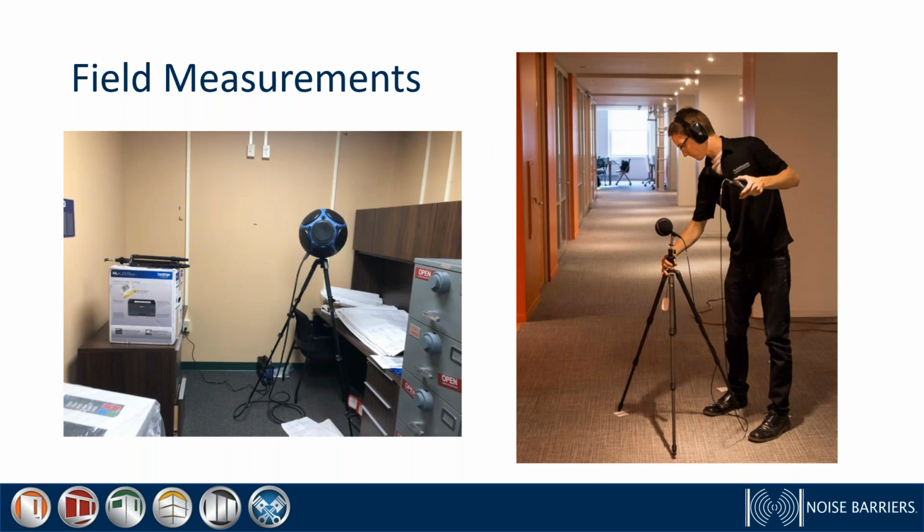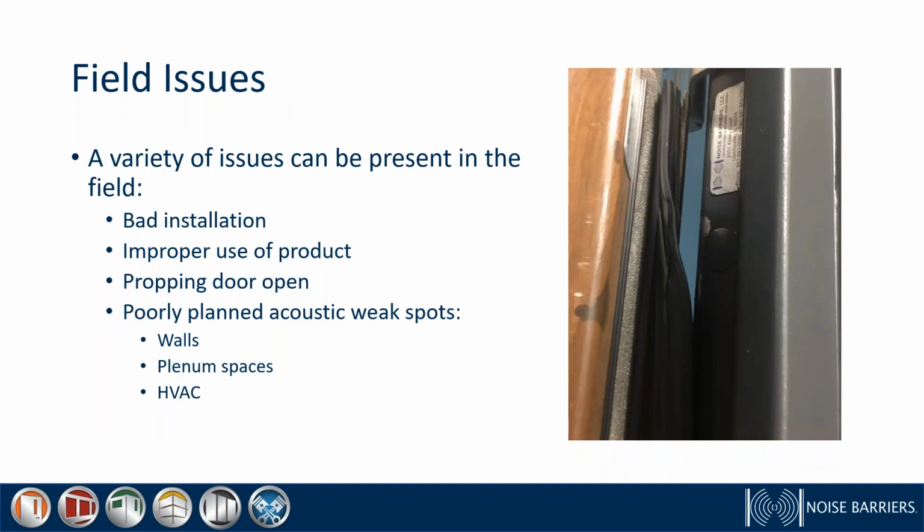So these are some photos from a riverbank field test that was performed. It was interesting to see the way the measurements are taken, the microphone outside of that storage closet or office area, and then that speaker with multiple angles where it blasts the sound throughout. So the computer will be set up and everything and the power amp, and they'll blast the sound through at all those different angles to see how much is getting through to the outside. And keep in mind, flanking paths can also come into play in these tests. So you try and isolate that sample as best as you can.